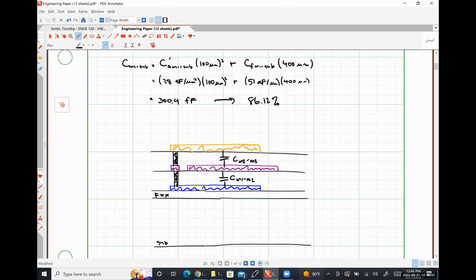So this is significantly going to increase our designed capacitance while keeping our parasitic capacitance effectively at a constant value. So this is a structure that we can utilize. That being said, poly-poly is probably your better way to go the overwhelming majority of the time.